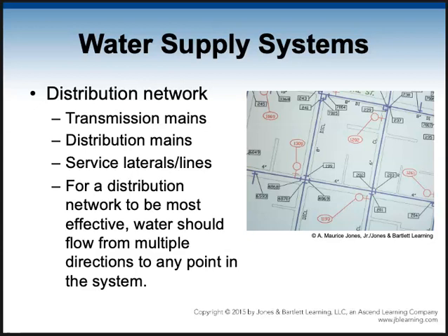So under the streets are all of these water pipes that go all over the place. A big boulevard will usually have a big transmission main, something 18, 24 inches in diameter. Then as you go into your avenues and your smaller, but still pretty big roads that go into the different parts of town, the pipes get smaller. And these will be the distribution mains. And then as you go down your cul-de-sacs or little streets, where it's going to serve and distribute off to different homes, that's where we get our service laterals. And these might be 8-inch or less in size.